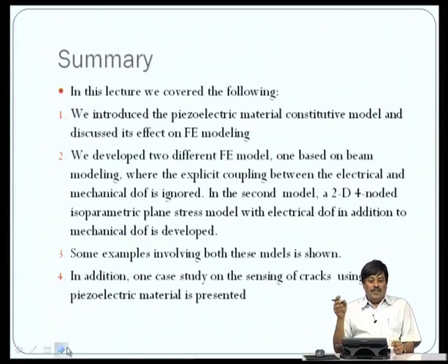Then we introduced another case study on how this can be used for sensing, where we showed how this can be embedded into a composite and measure the voltage because of the ensuing mechanical load, and tell about the state of the structure, especially with regard to the presence of a crack. So, basically we can use the piezoelectric material as a crack sensor for sensing applications.